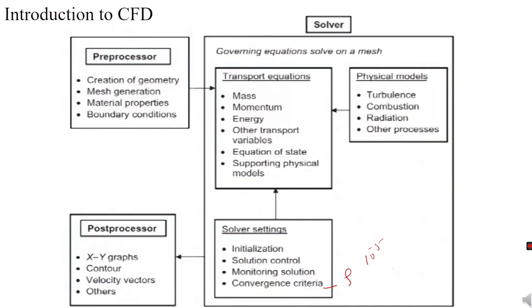Solver selection: understanding the nature of the flow, whether it is steady, unsteady, compressible, incompressible. You need to choose the right solver settings or models. And finally, with proper initialization, we can significantly reduce the computation time and improve the convergence.